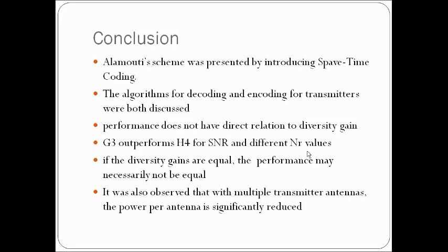The graphs presented in the results section show that the performance does not have a direct relation to diversity gain. This conclusion can be derived from the graph, as G3 outperforms H4 for SNR and different NR values. Also, if the diversity gains are equal, the performance may not necessarily be equal. This can be derived from the graph, since even though diversity gain is equal, G3 outperforms all.